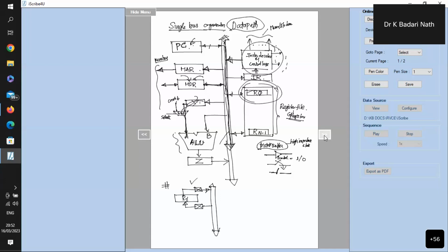Now I'll name this one RI, that is, the I register. So I am writing RI out signal. Now onwards, if I use it, what does it mean? That is the output switch connected to the ith register, which will be controlled by the signal. When RI out is equal to 1, that means RI is connected through the buffer to the bus.